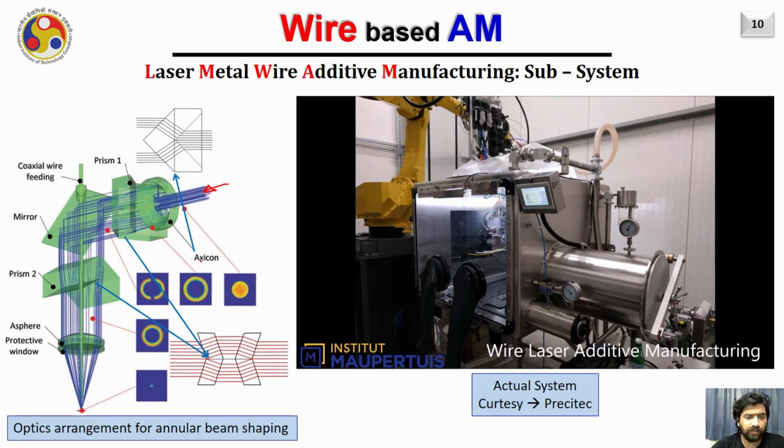The first optical system is a hexagon. Hexagon works like you are seeing here in this diagram. For example, this is the solid laser beam. Assume that half of the rays are traveling on the top surface and half of the rays are traveling on the bottom surface. The rays striking the top slant surface will get deflected in this direction, and the rays getting deflected from this particular surface will get deflected on the bottom side like this.